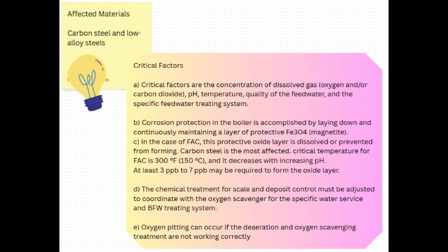You got it. And visually, the damage looks different again. FAC usually causes general wall thinning, not pits. Okay. But the key is where it happens. It's very specific, just downstream of flow disturbances. So right after an elbow or a valve or where a pipe narrows. Exactly. Any fitting that makes the water suddenly change direction or speed up. The turbulence hits the pipe wall right after that point.